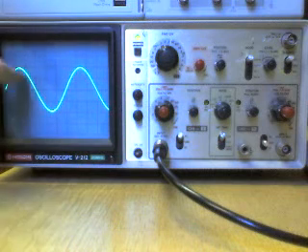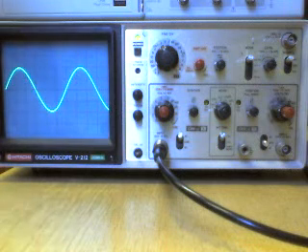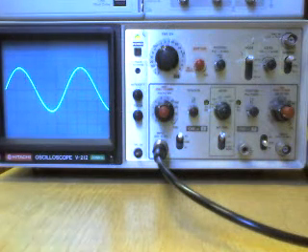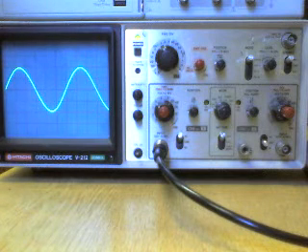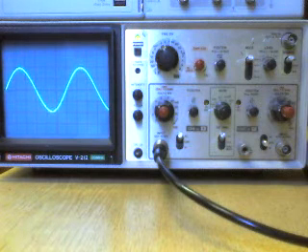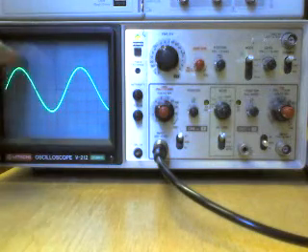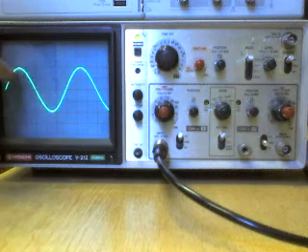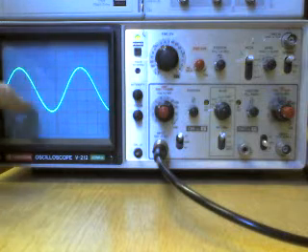You don't have to do it in halves, you can do 1, 2, 3, 4 multiplied by 0.5 volts. Again, 2 volts. We have 1 volt negative, 1 volt positive, 2 volts. Right then, that's how you measure your voltage. One cycle, peak to peak, 2 volts, because it's half a volt per division.